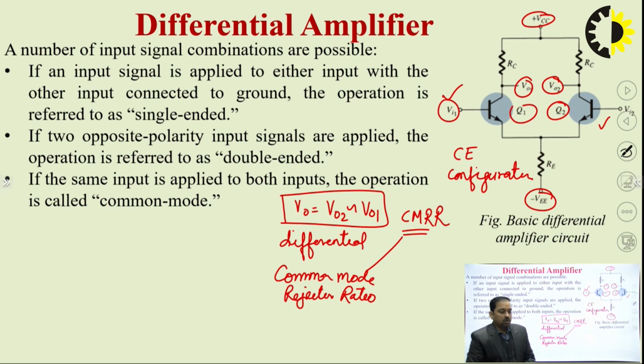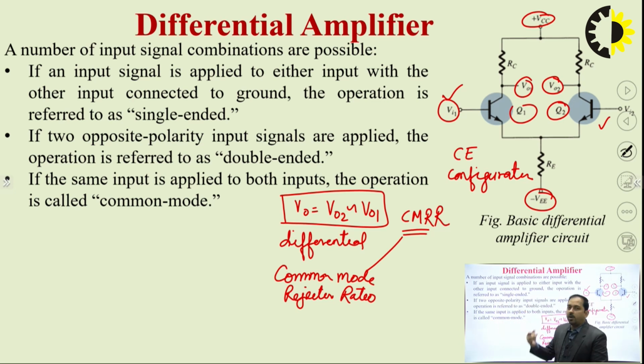That means all the common mode signals applied to this differential amplifier or operational amplifier get rejected, whereas the opposite polarity signals get amplified.